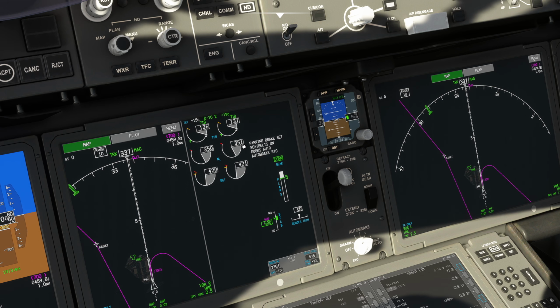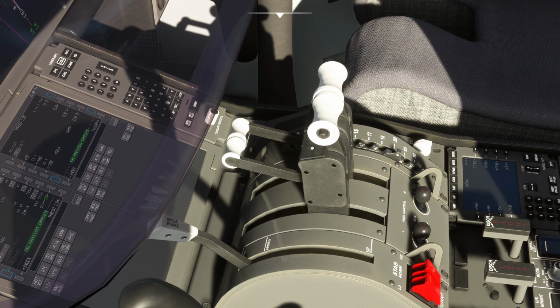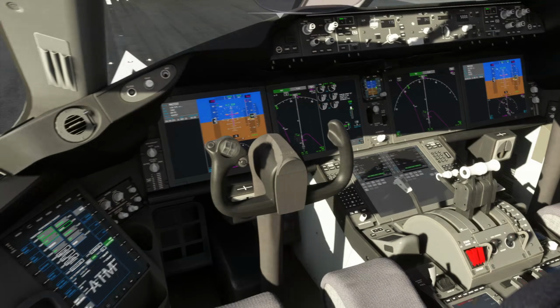Typically, if you aim for this decimal point, it should get you close to 20. In the real aircraft that would work, maybe a little bit less on this one. And there you go, it gives you somewhere around 45% N1, that's pretty reasonable. Somewhere between 40 and 50%, nothing too dramatic. From there, you then press this button here, and then the aircraft will start rolling forwards.